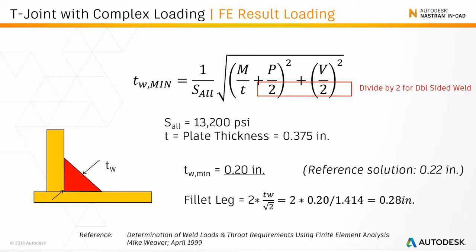Again, this could be done in minutes versus what could take many times longer using hand calculations. And note that the weld size is divided by 2 as we've got welds on either side of the plate, so it's a double-sided weld.